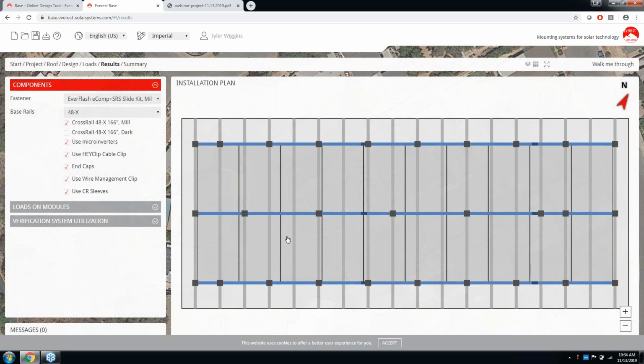Basically, that rail is existing in between these rows of modules. So for aesthetic reasons, you really have two options here for shared rail. You can use a skirt on the front to hide that rail if you'd like. The second option, if your module allows for it, is to tuck that rail up, where it's now going to be mounted on the quarter point on the long side of the module, and also on the quarter points of the short side. An important thing to note if you're going to be tucking the rail is to ensure that the module manufacturer allows for that mounting option in their assembly guide. So that's something important to check on.